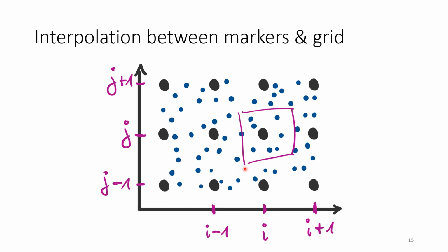So which means I'm simply not solving the advective terms as a hyperbolic PDE here. I'm solving my advection by having those points which are moving with the flow field. And then simply through interpolation, I'm getting the information from those advective points.